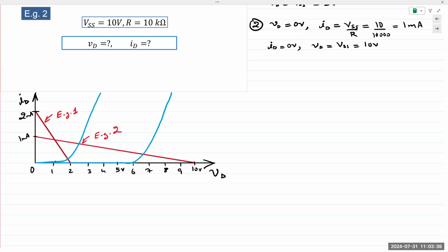In real life, I think one of the most common applications for a diode is in a digital thermometer. The reason is because the diode's characteristic changes very linearly with change in temperature. So there is a very simple circuit comprising 2 diodes and 2 sources, and it just compares the 2 points. Depending on the temperature, the diode voltage or current shifts up or down.